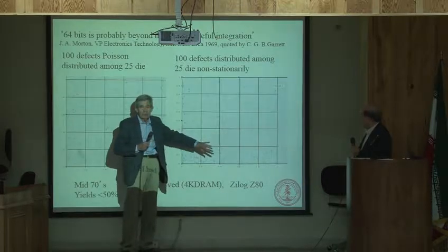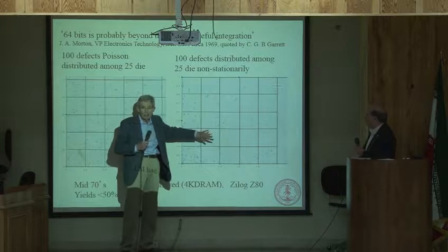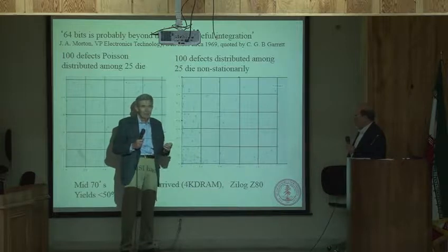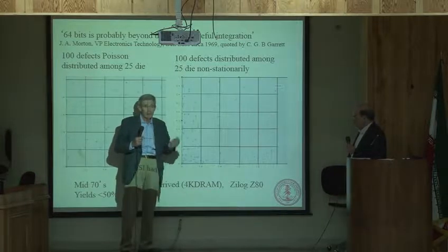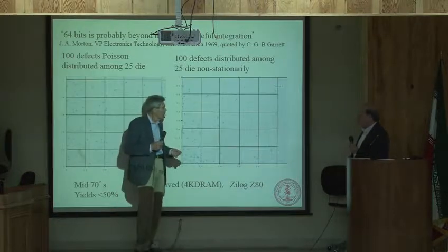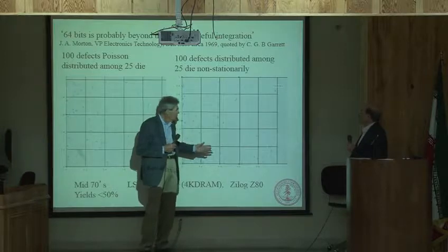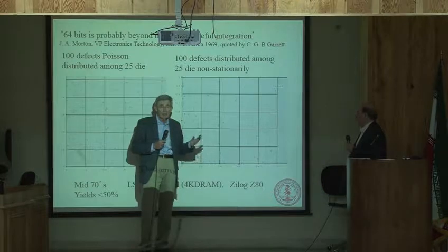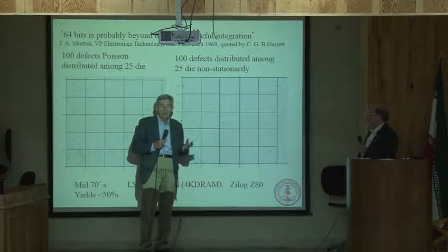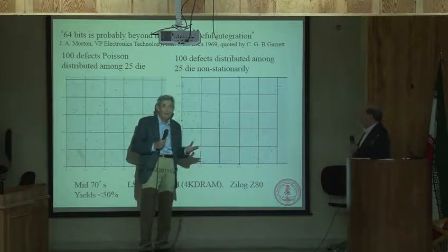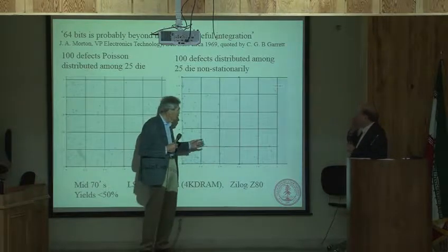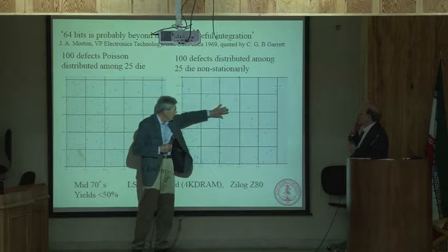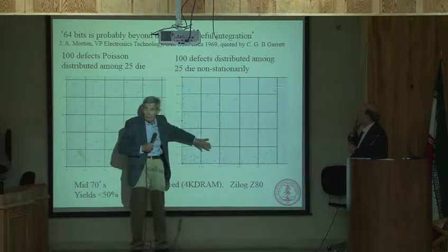Another very frequent issue: you have to decide what you mean by yield. In the research lab, if we can get a circuit to work in a very narrow window, that's all right. We can publish our paper and move on. But in any industrial setting, a circuit has to work over certain windows of the power supply levels, temperature, humidity, stress, or whatever. And so you put your circuit through all those tests, and you find that things like the threshold variation might be rather slow across a wafer.